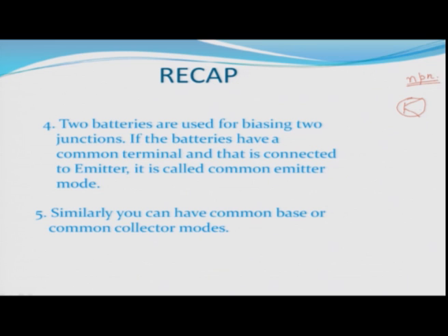So, if you have this NPN transistor, this will be the arrow. Then in this emitter side, if I put this emitter base junction, this has to be forward biased. So, if this is P, you have to put a positive battery here, some resistance of course, and it goes like this. So, this junction is forward biased. So, this is a battery used for forward biasing this one.